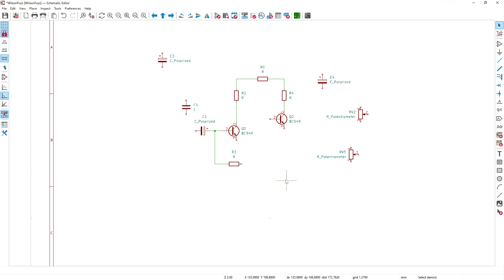If you want to draw a wire, you can press W, and it's a random wire here, and then you can right click and finish. It used to be a different key, I think it was K. I don't know why they changed this. It's a pain because my keyboard is awkward, I need to use both hands to type, and you can undo with Control Z. If you start from here and you want to connect it there, it's easier, right?